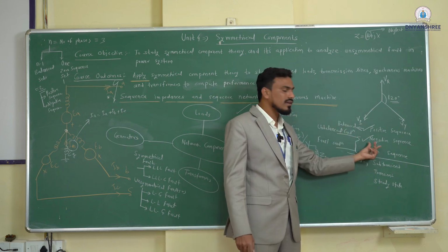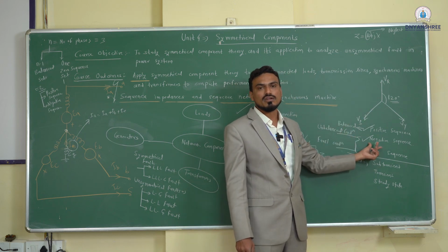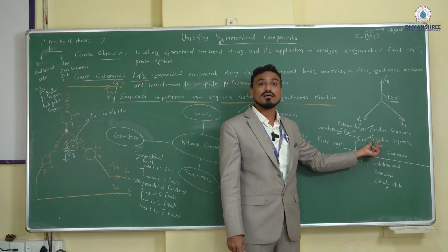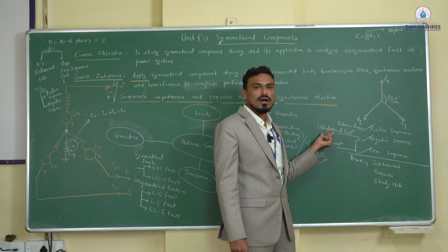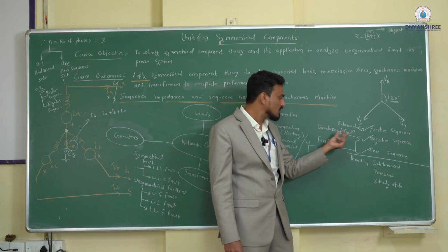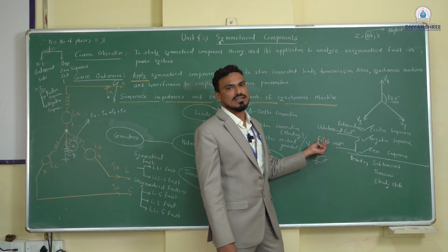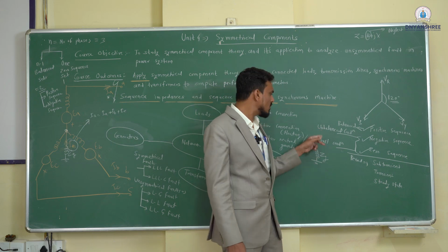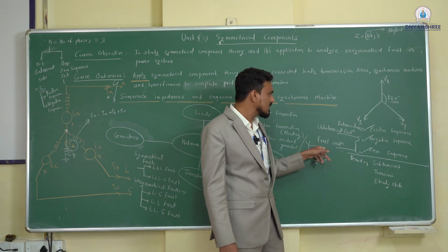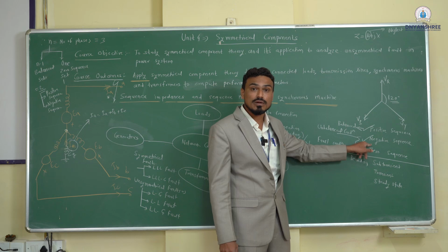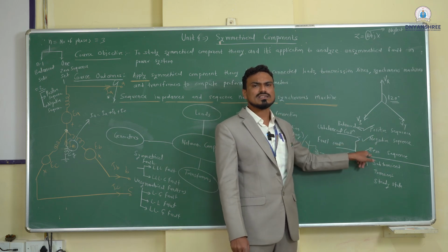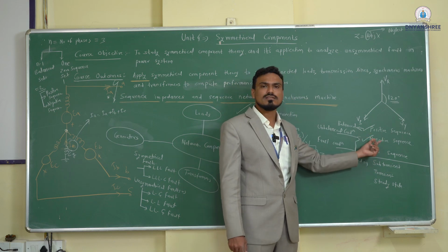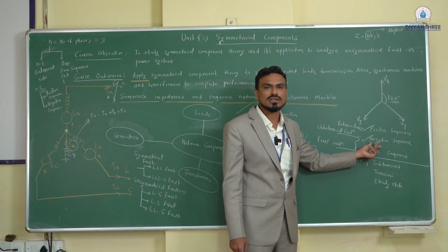What is happening in the case of negative sequence? The negative sequence component is present mainly because of unbalanced loading conditions as well as fault conditions. These two conditions cause the presence of negative sequence components as well as zero sequence components. What are their consequences? Let us discuss negative sequence first.